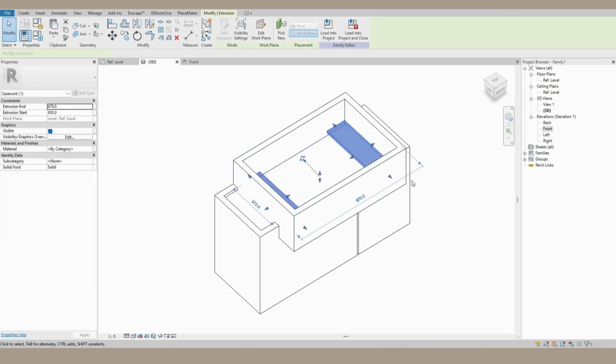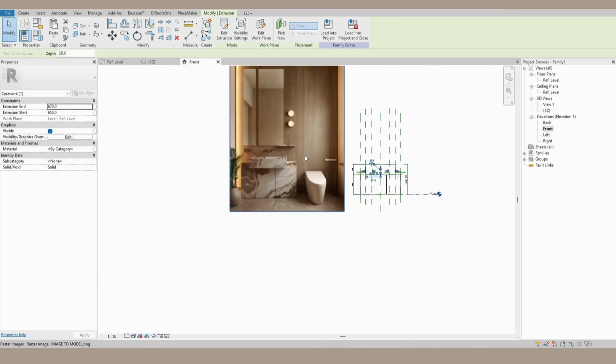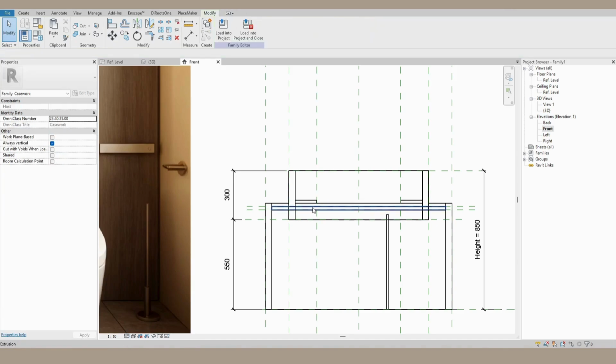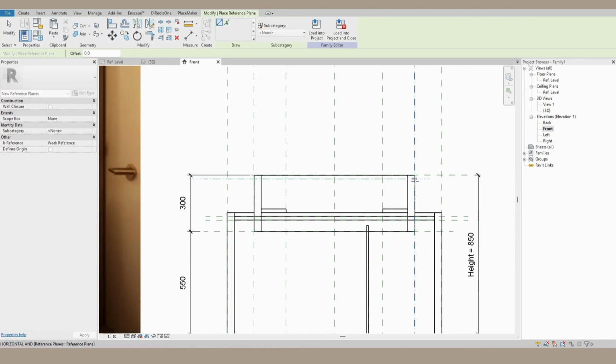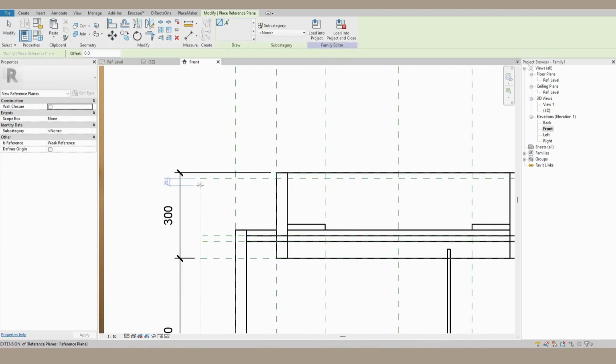And with that, you're going to make sure that there is a 30mm lip as well that matches the bottom. It's all about symmetry here. It is all about aligning your elements using reference planes. I think that is really the activity here, and it's a good takeaway if you can do that, because that's half your job done, to make sure that it's accurate and can easily be maneuvered and changed for the future.